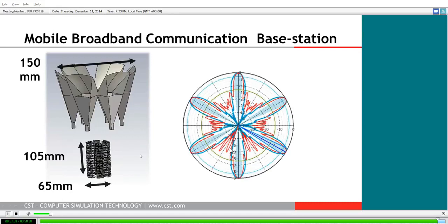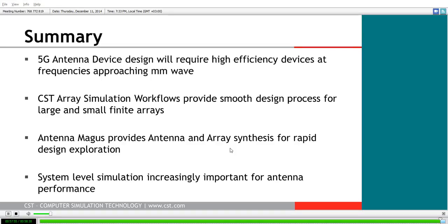More importantly, though, when we actually look at the resulting form factor, our arrangement of waveguide antenna arrays is providing us with the required gain and coverage with a much smaller form factor, particularly in terms of the width, compared to the sectoral horn antennas. So this likely makes it a much more attractive candidate for subsequent in-detail study for the design.